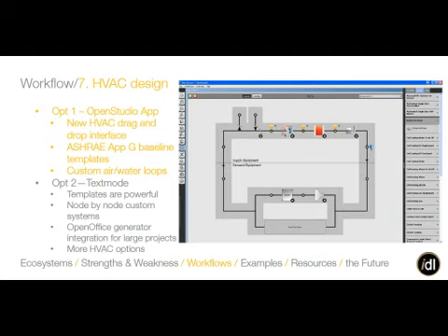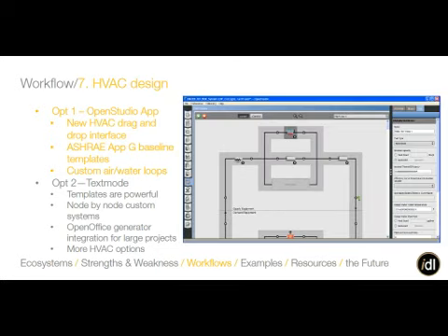So, like, if this was a VAV system, you could do VAV, reheat, hydraulic, or electric, in some of the ductwork. But the nice thing about these is essentially it takes care of all of those ductwork connections and pipework connections for you in the template system. If you did it custom from scratch, you would have to define all those yourself, which very few people can do, and it just takes a lot of time.